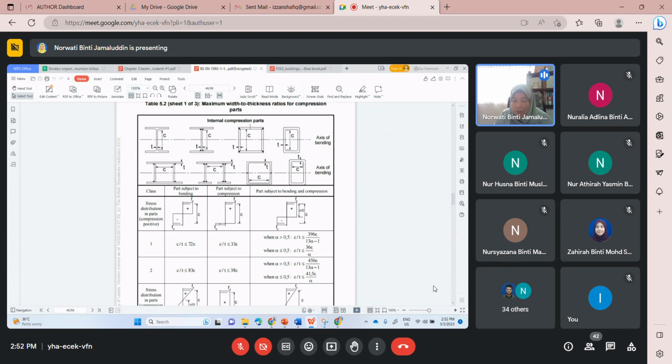This one is also a built-up section that forms the rectangular shape. This one is a rolled section because there is no welding here. It is smooth. We have quite smooth corners here, based on the radius. So that is what the diagram means. Okay, back to our case. We are using an I section, so we can use this table.